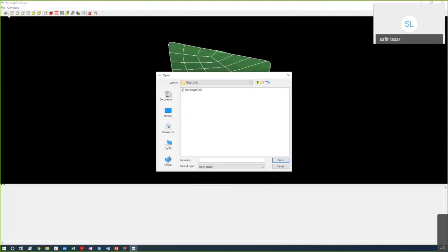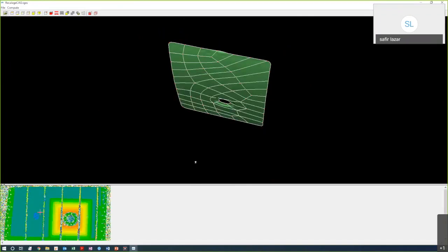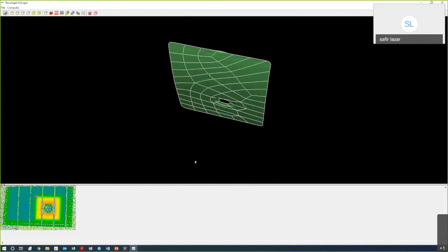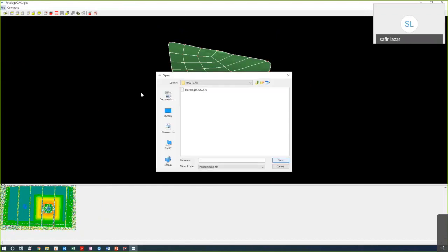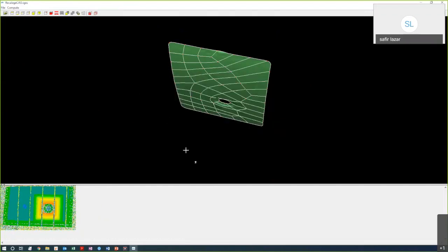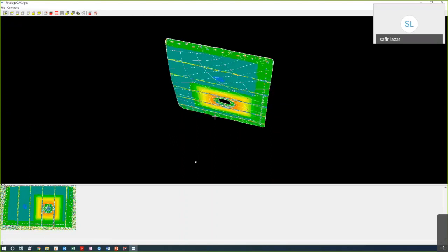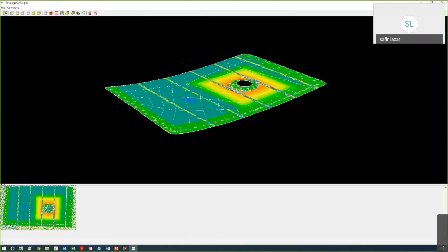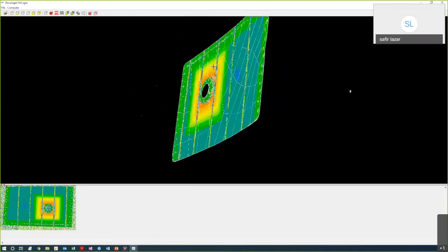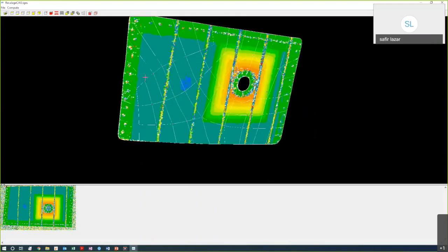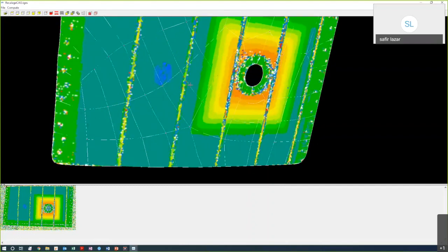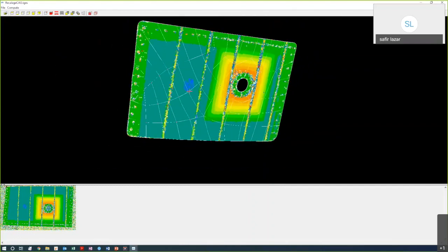You can here open an image. So it's coming in the bottom. And I will manage some CAD fitting. You can load some points directly on your cartography and compute and apply a texture. So the image in the bottom is directly applied on the 3D part. With this feature you can put your C-scan directly on your part, and so you have a better idea of where the defects are or where my C-scan is on my part.